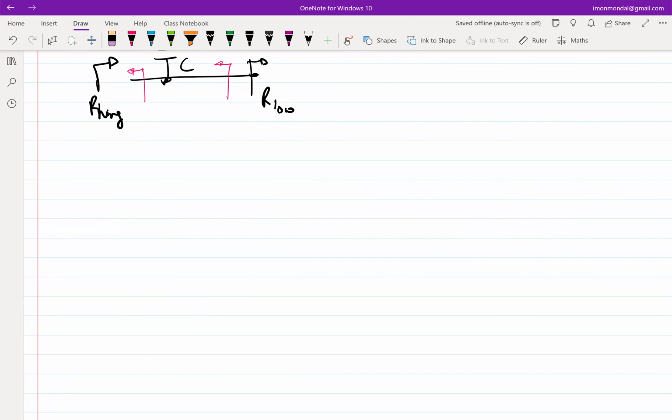So now, once we have this framework, you should be convinced that no resistance is too small or too large to implement matching. RF systems at the input port require matching. If I see some resistance lower than 50, I can step it up. If I see something higher than 50, I can step it down. I have a matching network to play with. So we are going to use these types of matching networks without thinking twice about it in later lectures, as and when required.